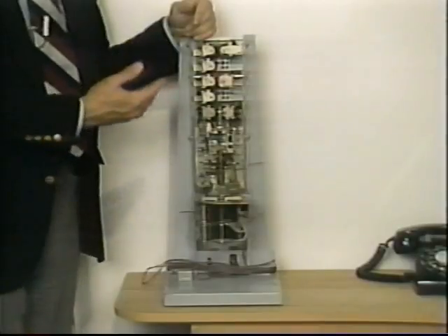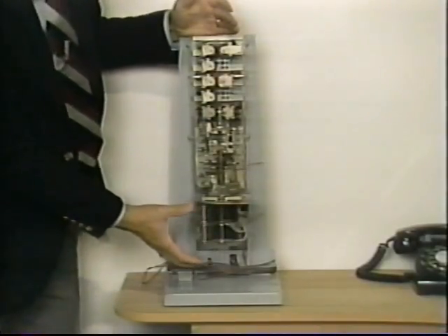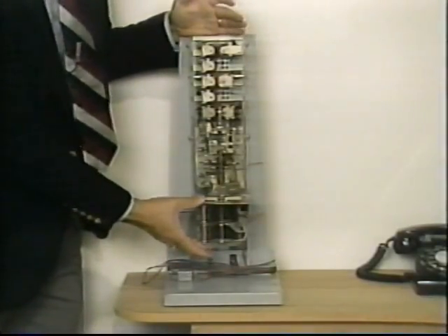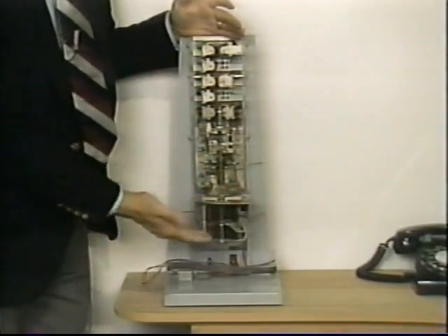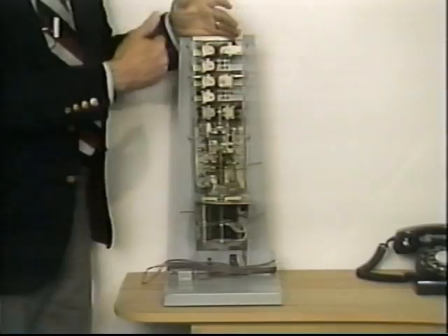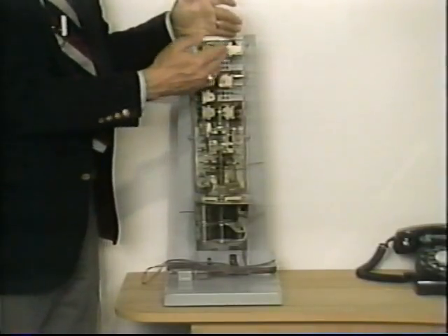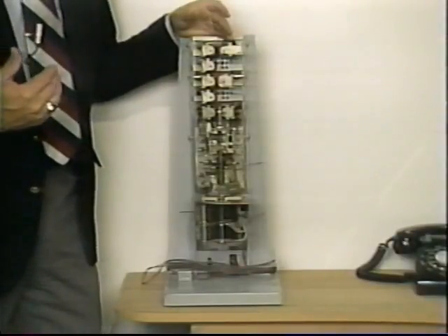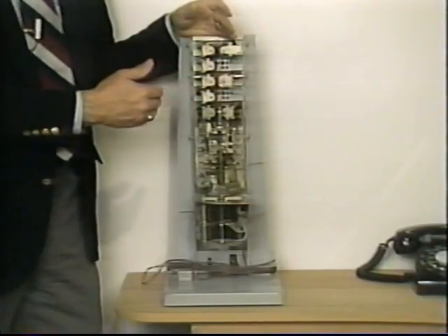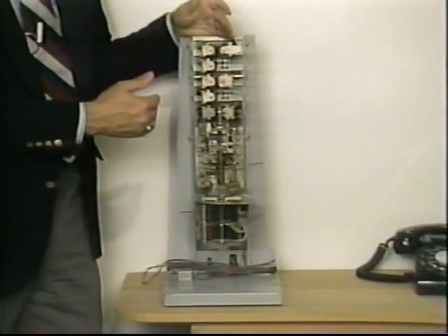Now, looking again at the whole stepper switch here, all the switching function takes place down here. Up here, what you see is the mechanics that actually move those wiper arms and control the connecting of the call. There are relays here that make sure you're not really connected during the switching so you don't get all the noise back and eliminate certain electrical interference problems for you.